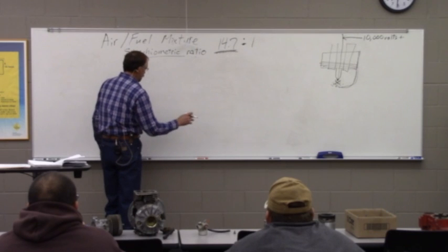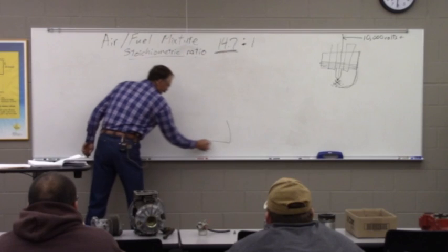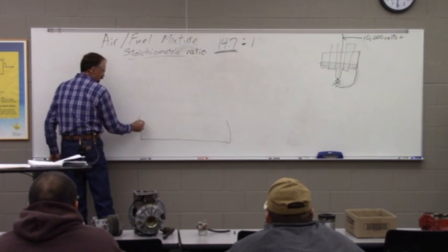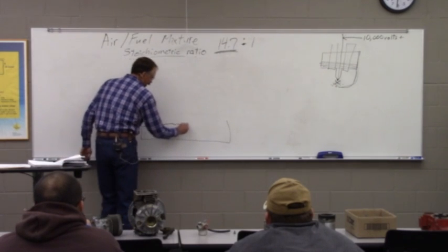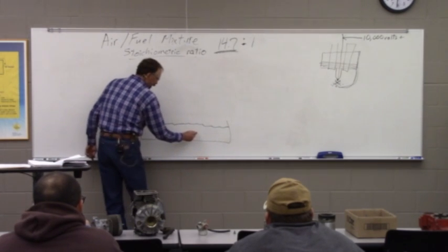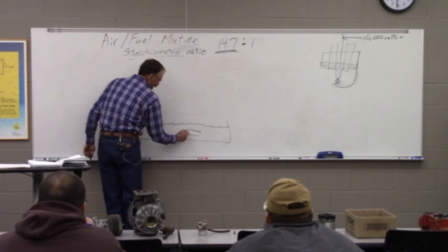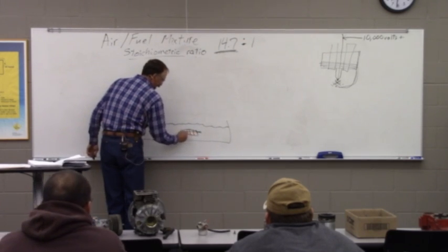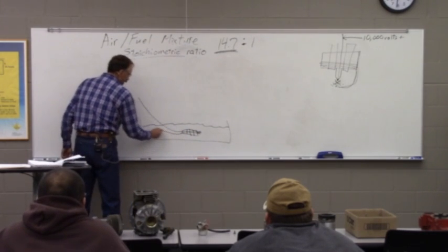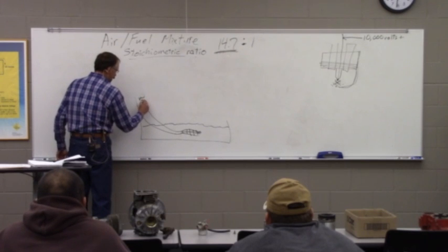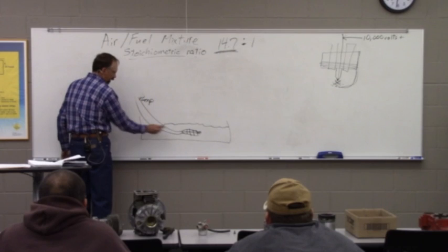2 little things that I wanted to talk about on that. So we're going to draw, most all our automotive engines are going to have an oil pan on the bottom, and we're going to have liquid oil in here. We're going to have a strainer that's kind of like a coarse screen here, and a pipe coming up to our pump. So the pump is going to be above the level of the oil, and it's going to suck the oil up here.